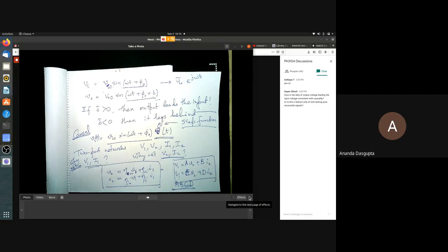At the same time, suppose in the Z parameters you are trying to measure Z11 or Zi. That's V1 by I1, small v1 by small I1, of course, with small I2 equals 0. So you have to set small I2 equal to 0 by AC shorting out the output, and connect the current source to the input so that you can drive a known current through it, and measure the voltage at the input. So in a way, you have to have access to both the input and the output simultaneously.